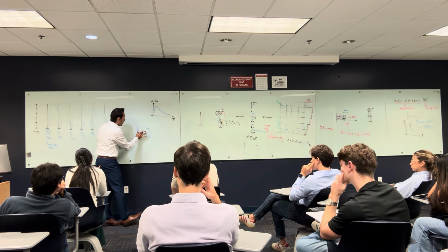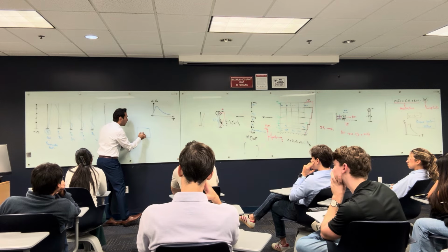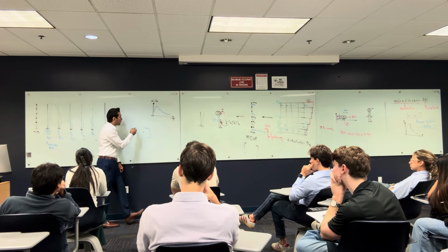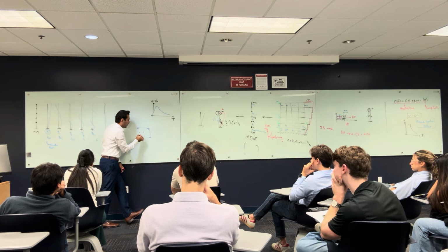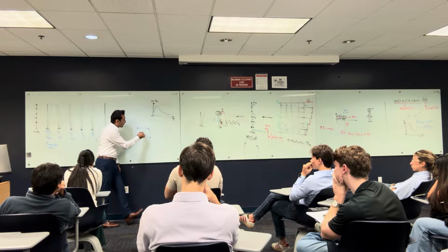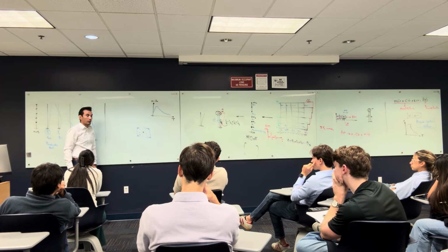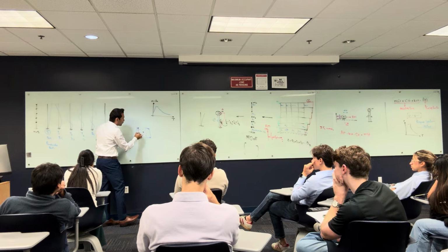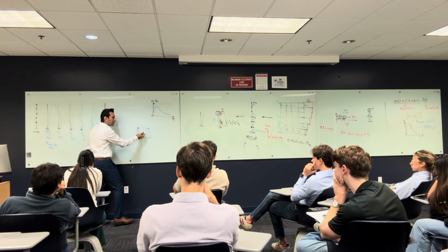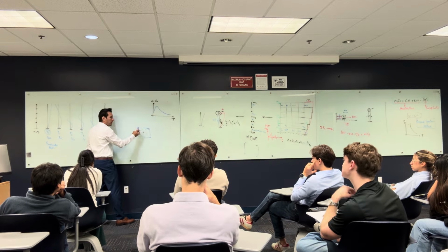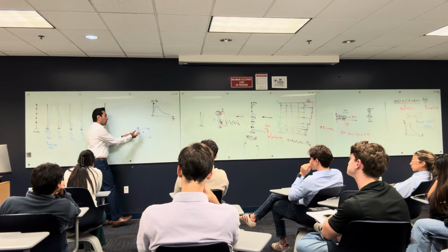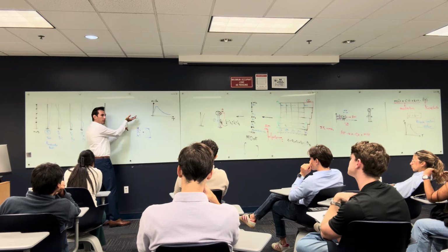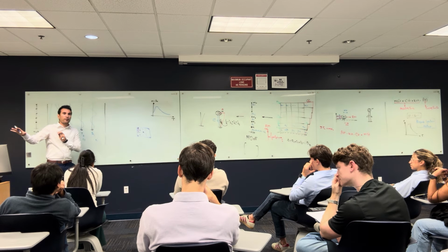So the thing is, before you have this wall, the center of mass was in the same place as the center of rigidity. If the distribution of the columns is symmetric, like something like this, and you have a column here, column here, column here, column here, the center of mass is at the center of rigidity. But once you convert this column to a big shear wall, you make the center of rigidity move towards the shear wall. Like it's gonna move that way, for example. Because this shear wall is to the left and up, so the center of rigidity is gonna move up. There are methods that you can use to find the center of rigidity.